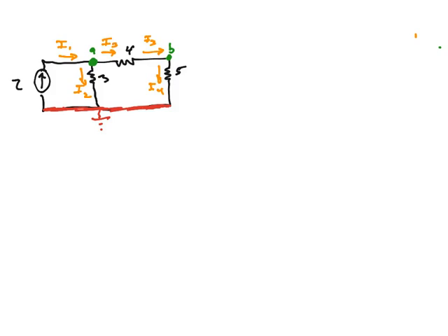All right, so for each node, all the wires are labeled with currents. Some are coming into the node, some are leaving the node. And notice what's important is this branch that has the 4 ohm resistor sitting there. Because all that's there is a resistor, that current that left A doesn't split. It stays as the same current, so the current that leaves A is the same value as the current that comes into B. That's why I call them both I3. I don't have to change it.